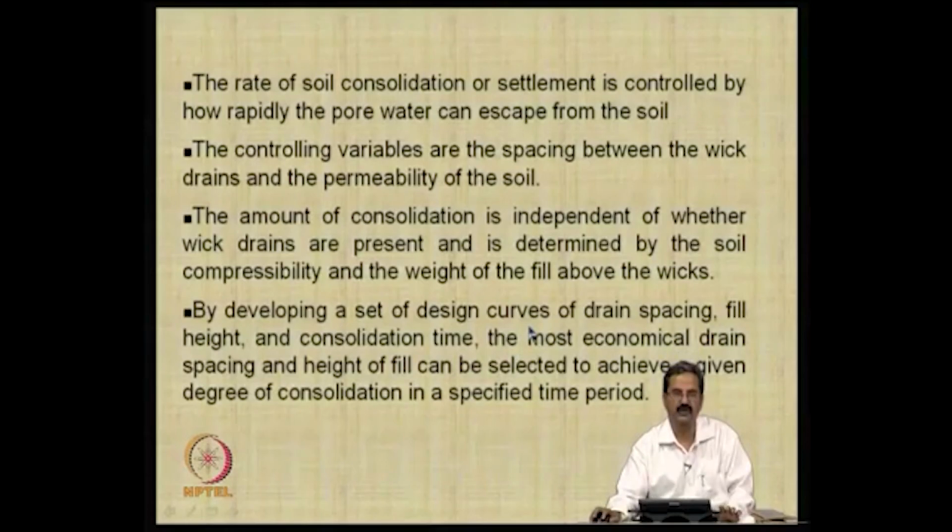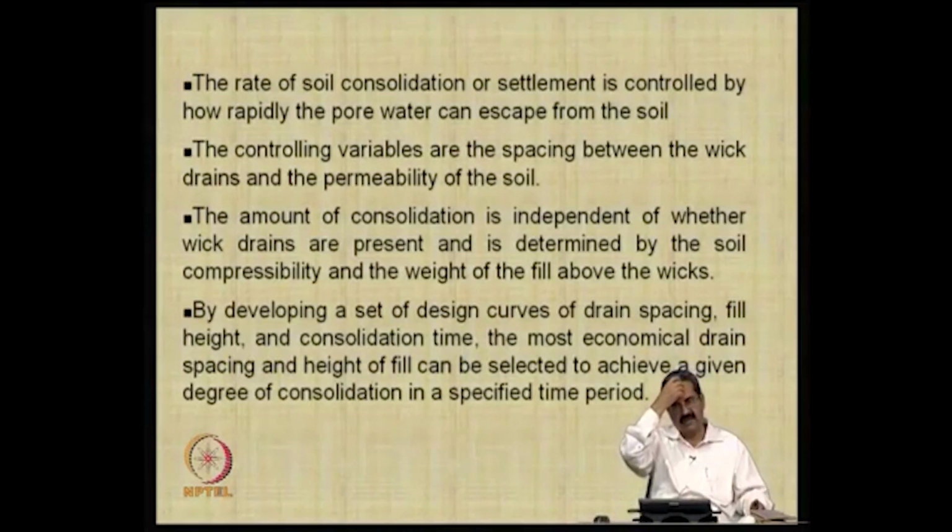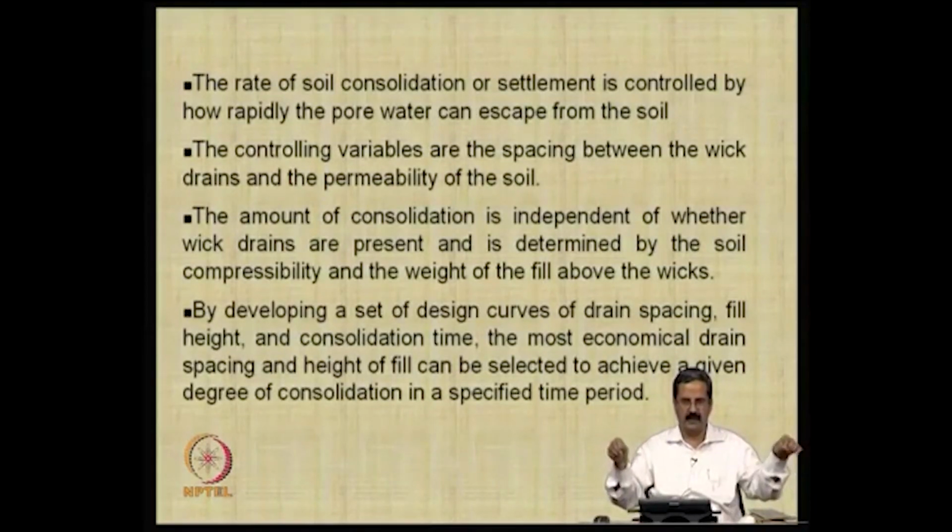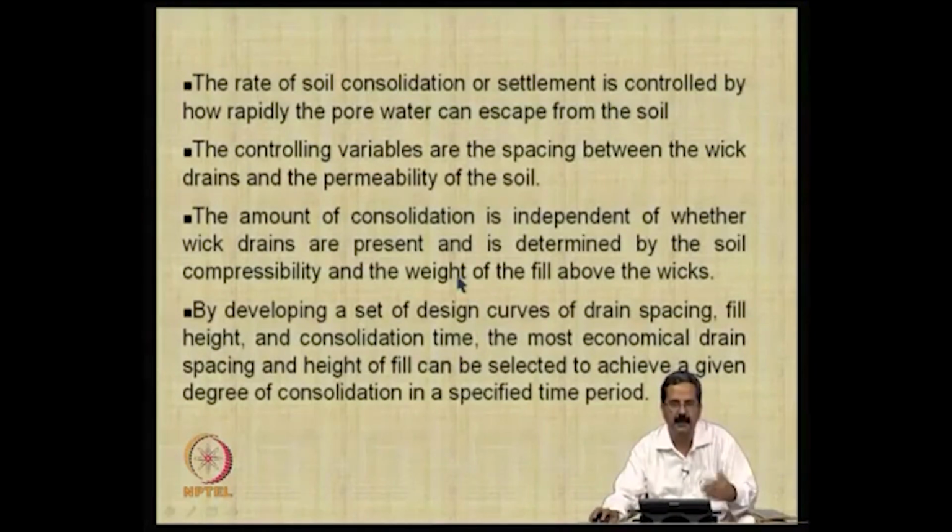What we do is develop a set of design curves of drain spacing, fill height, and consolidation time. There are 3 or 4 variables here. You also have the preload, but if you want to minimize the preload, you have to see what spacing you should provide. If you provide a wider spacing, the preload will probably be higher, but if you want to reduce the preload, then you need to come back to a closer spacing.